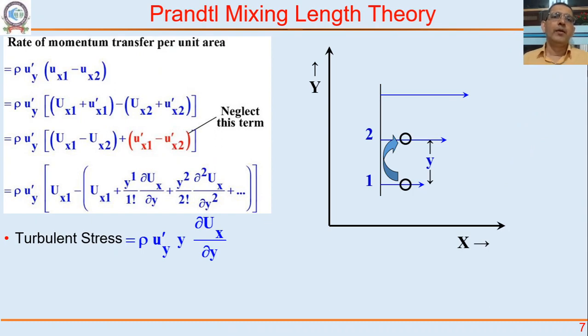Okay. Now we talk about, like when we derived stress terms, viscosity, effect of viscosity, molecular motion, same way we are going to do. Let's assume that there is a velocity profile Vx. Vx is changing in the y direction, right? What does that mean? dVx by dy is non-zero, right? Do you recall? Vx is changing with respect to y. dVx by dy is non-zero.